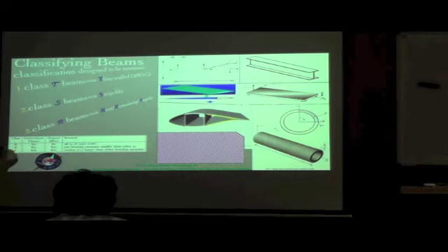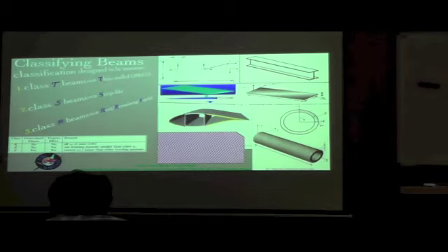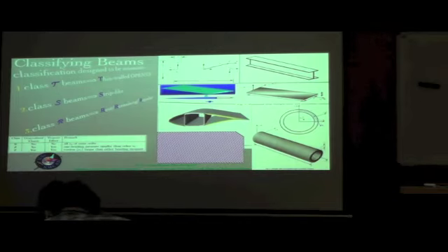Next we look at the S-class beams, and the generalized Vlasov effect, the restrained warping, doesn't affect those. That is not very clear right now in terms of a physical explanation, but when you see the mathematical derivation, you will see that kappa 1 prime does become important, but it is not of the same importance as the trapeze effect. In other words, the trapeze effect is much more critical, and therefore this will come out as a higher order refinement, which for most engineering applications is not necessary, and therefore you see that the generalized Vlasov is not very significant there.